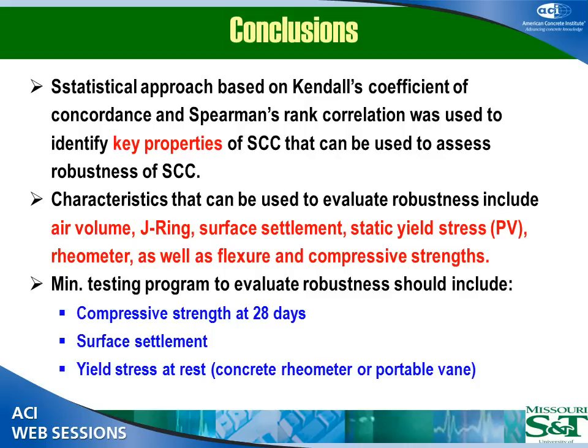And this is what Dr. Rousset was talking about, that within plus or minus 10 liters, you know. And the superplasticizer, if you're using a superplasticizer, say at 0.6, 0.5 liters per cubic meter, so you're looking at about plus or minus half a liter, which is within the precision, if you would. Okay, thank you. We could make it a lot higher, but we want our SCC mixtures to be better, tighter control, and that's what they need.